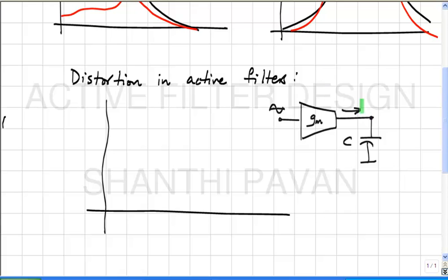Okay. Now in practice, how is this resistor going to be implemented? It is also going to be a transconductor fed back on itself as shown here. Correct? All right. So we understand that if the input transconductor is nonlinear, it also follows that the transconductor which is used to realize a resistor by the same token should be just as nonlinear. Does it make sense? Correct? I mean, if it doesn't, then I would remove the first transconductor and use that transconductor as the main transconductor. You understand?